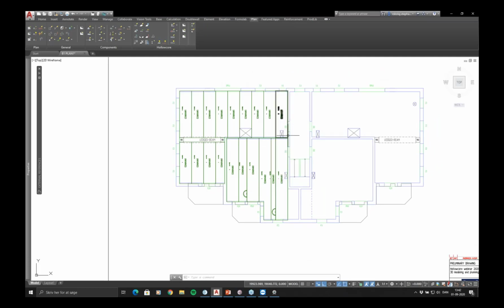And as I mentioned before, I have some holes, or some recesses as we might call them, here. And I was a little bit too fast because I forgot to tell what I was doing there. What I want to do is pick this one up here, draw recess. So now we get into components. This is if we want to add some stuff, subtract some stuff or something like that, we're using the components.